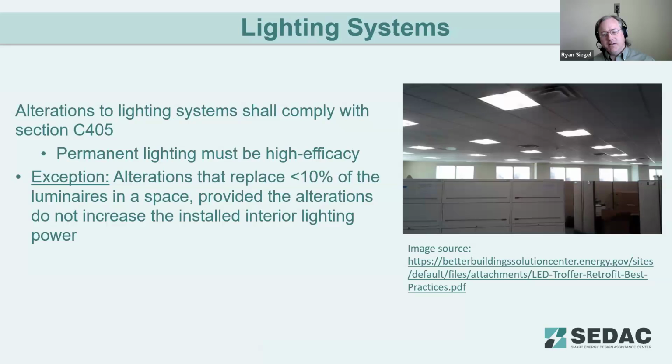So, lighting does have a provision in there noting, yes, you do need to comply for new lighting systems. There is an exception for alterations that are replacing less than 10% of the luminaires in a space, not in a building, in a space. So that's trying to note that, hey, if you need to replace a fixture for some reason, we're not going to throw that into the full compliance requirements. So that's a fairly low threshold to hit.